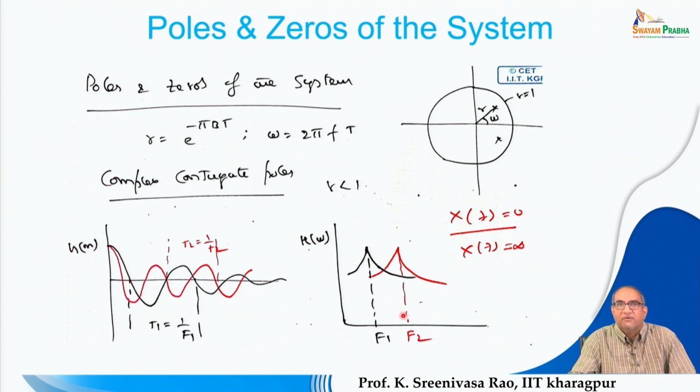And for example, if there are two pairs of poles, this is one pair of poles, and if there is another pair of poles somewhere here and here, right, this pair of poles offers a frequency f1, for example the black one, and another pair of poles somewhere here, where the angle is more than this one, will offer another frequency here like this, right.